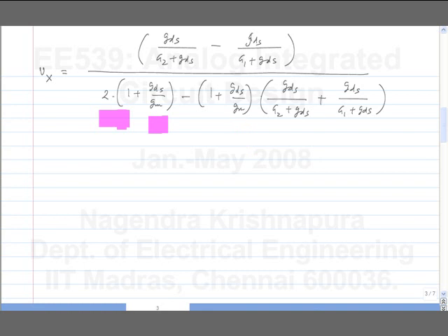So also, you have GDS by G2 plus GDS and so on, some other things. Roughly speaking, the denominator doesn't change too much with the relative value of GDS, except of course if GDS is 0, it's a different thing. Now the numerator has GDS by G2 plus GDS. So if G2 is much more than GDS, then the absolute value of the numerator becomes small, even if G1 is different from G2. Is it okay?